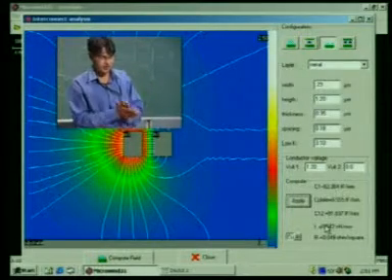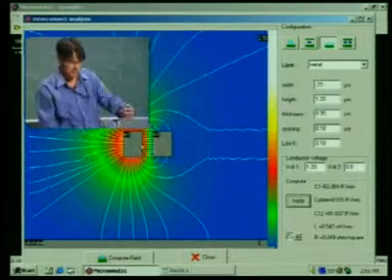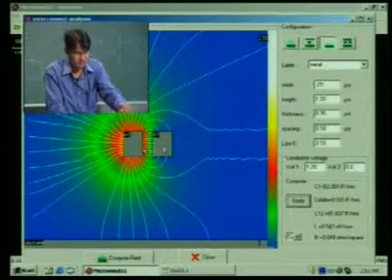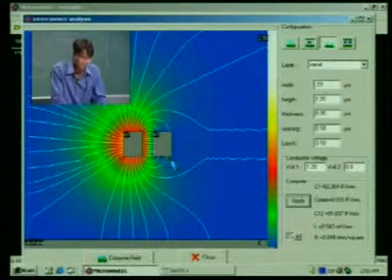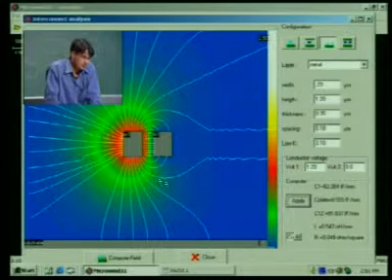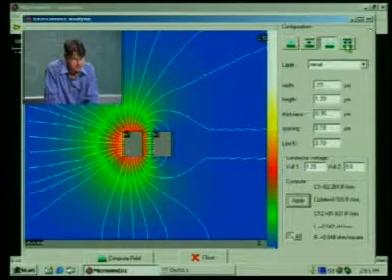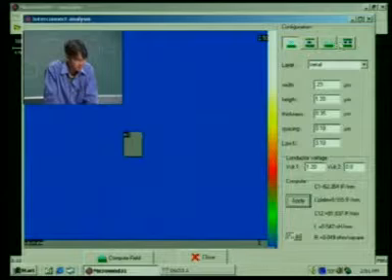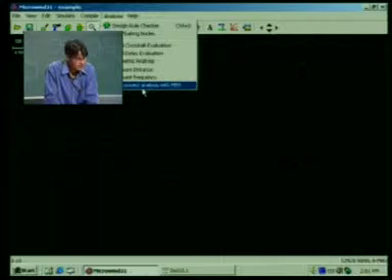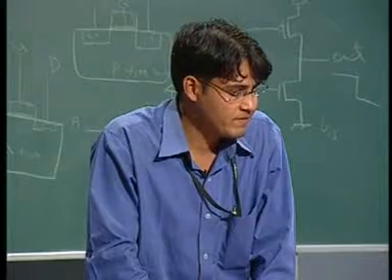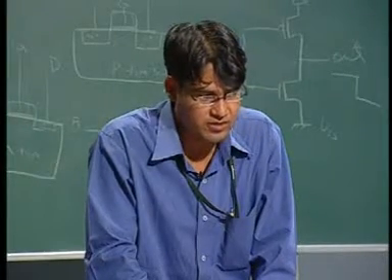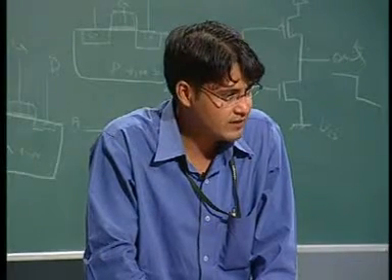Okay, this will not now create the crosstalk effect. Crosstalk is interference, it will interfere with other signals, so definitely there may be some difficulty. So this proper analysis should be there. There are different kinds of analysis, they have provided a lot of options here. We go for resonant frequency analysis, then parametric analysis, then global crosstalk evaluation, it will give all the data.